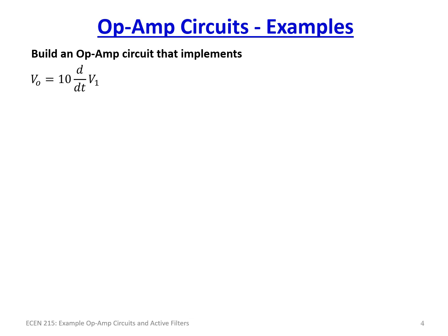It does not matter. So to do this, what I've decided to do is first invert the input and actually apply a gain, and then push it through the differentiator with a gain of minus 1. So we're going to have first an inverting amplifier. And just as a refresher, the stage here, this is RF, and this is RN, and this is V1. The output here is minus RF over RN times V1.